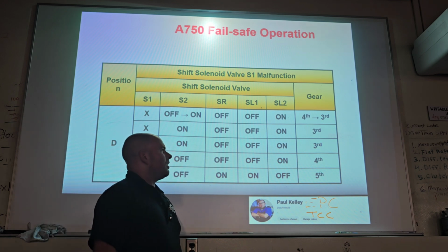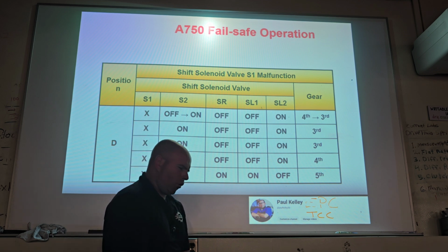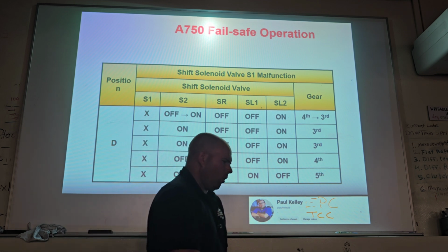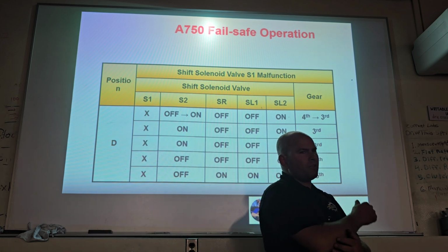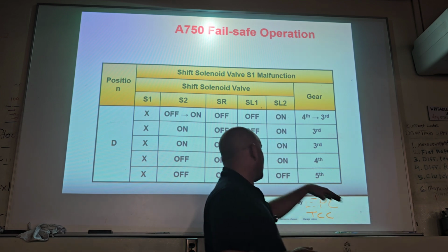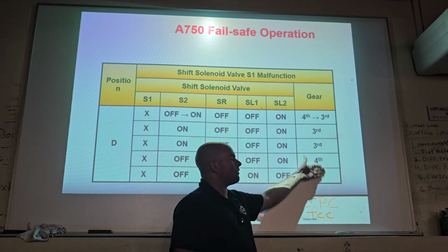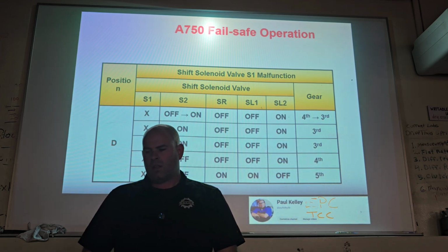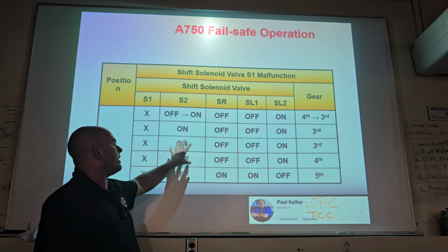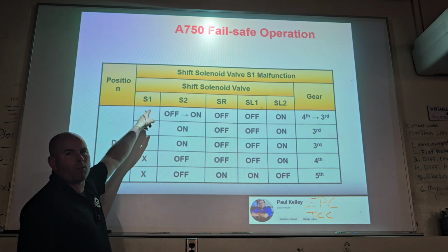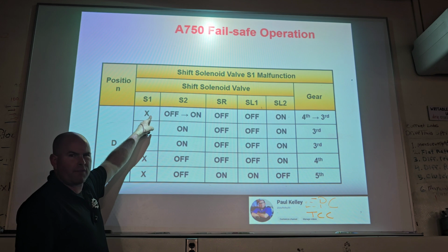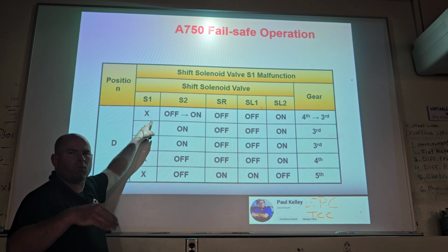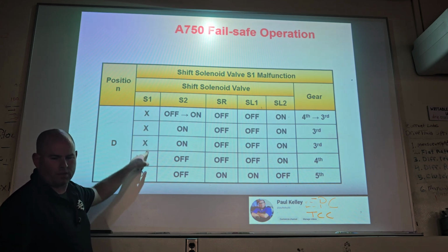So this one driving, third. Well, actually, it's more like third. It's going to be really slow, but then actually third, fourth, and fifth right here on the freeway, it's going to drive fine. That would be specifically employed only if it knew that there was a problem with S1 because it detected a circuit failure. Make sense? It's constantly watching for voltage drop on that circuit.